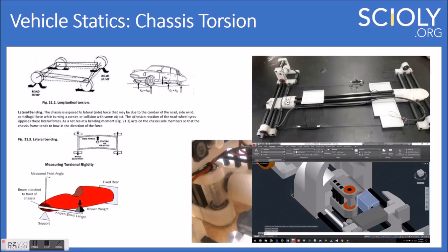And as you can see, with this carbon fiber frame that we implemented, it actually took care of a lot of the torsional parts. It was able to just twist based on the road just slightly and compensate for any imperfections. Whereas if you had just used a piece of plywood as your entire frame, it wouldn't be able to do that unless you had some sort of suspension built in. And suspension can be quite tricky to implement properly, and it can give you a lot more problems in other areas, although it is something I do wish I had looked into.